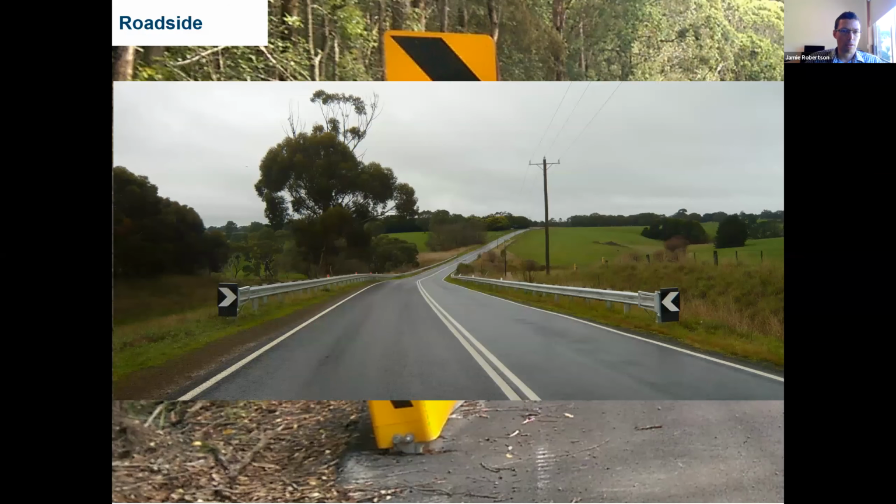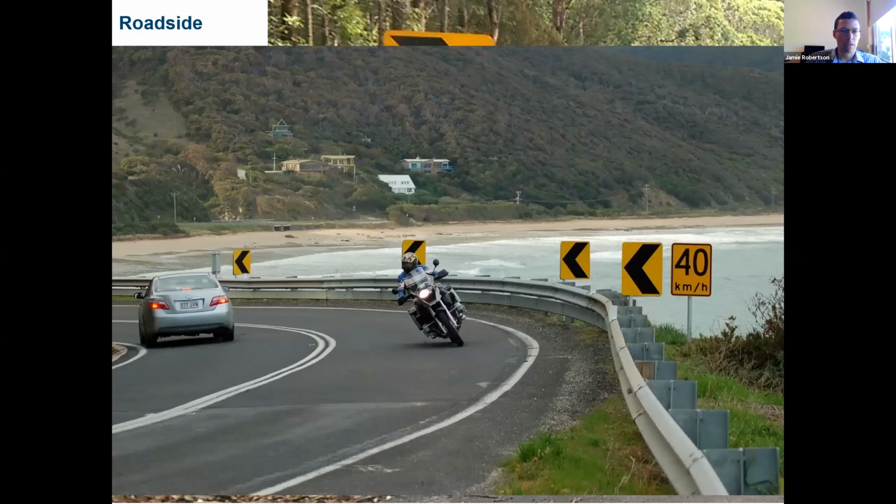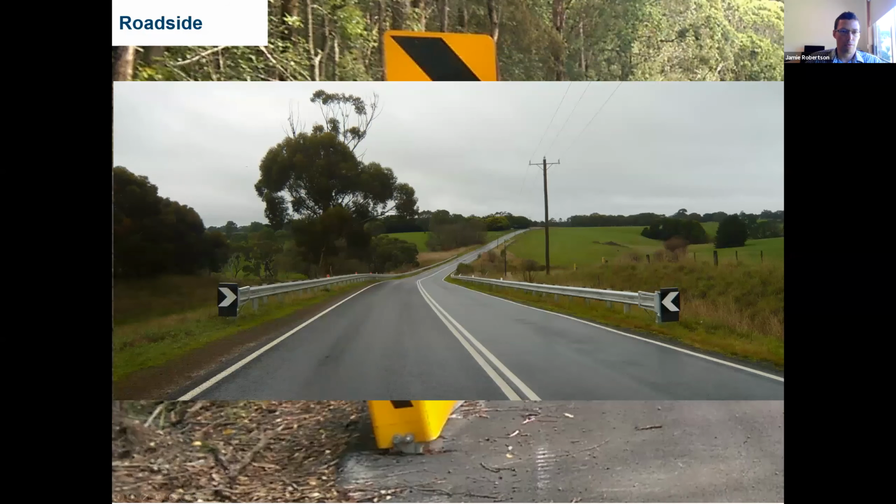Another guard fence at the roadside. So here we really are concerned about that possibility of an errant vehicle entering the roadside and striking a tree, rolling over. In this case, we have a structure at the bottom of the hill. So there's that possibility of the vehicle striking an object or crossing onto that non-traversable batter.